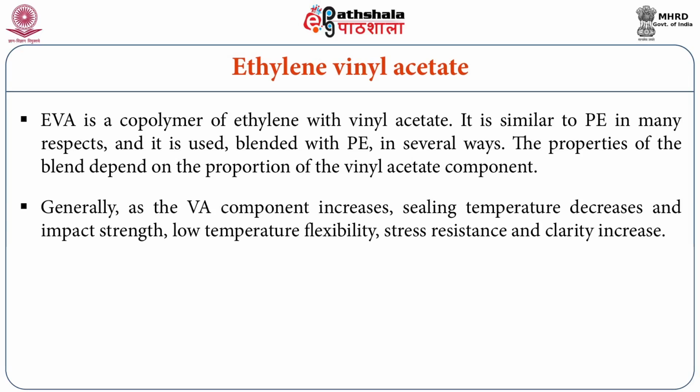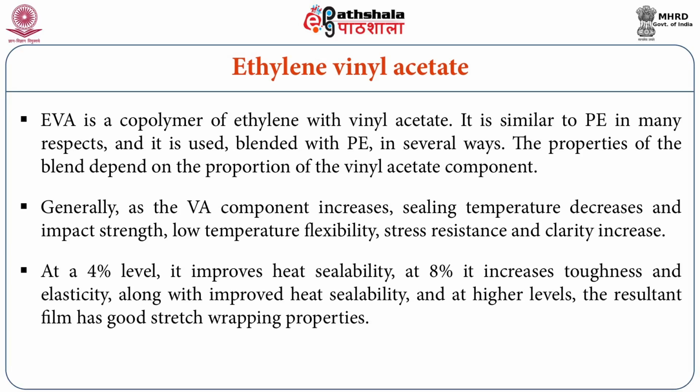Generally, as the VA component increases, sealing temperature decreases and impact strength, low temperature flexibility, stress resistance and clarity increase. At a 4% level, it improves heat sealability. At an 8% level, it increases toughness and elasticity along with improved heat sealability. And at higher levels, the resultant film has good stretch wrapping properties.